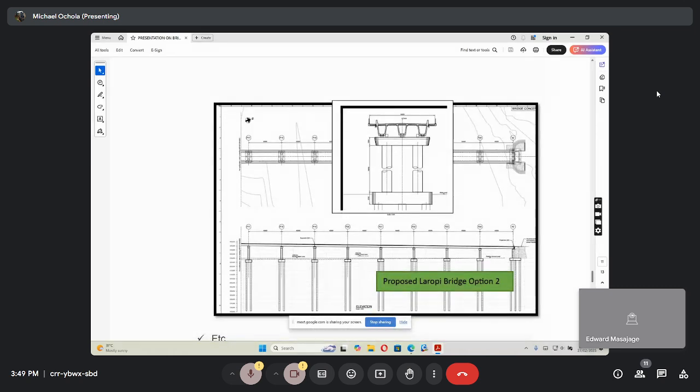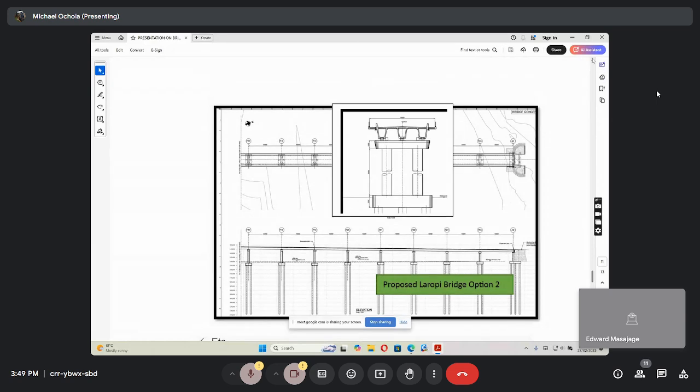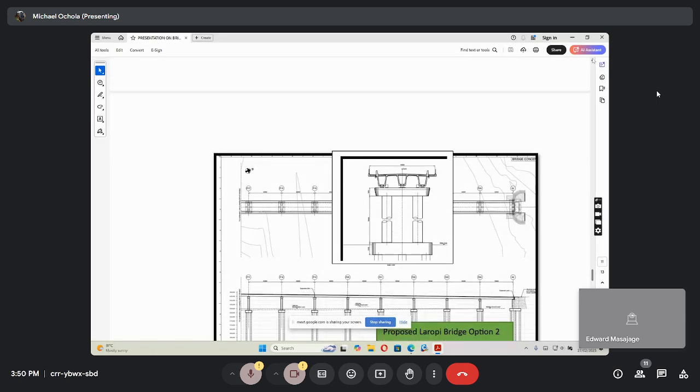So option 2 is not a cantilever. No, this is a normal beam, but they are continuous over three spans. So like after every 120, you put an expansion joint. So the expansion joint is also a component of a bridge. Please look at the expansion joint, add on your parapet and crash barrier, and add on your bearings. Those are part of your bridge. They are all structure. They must be designed.